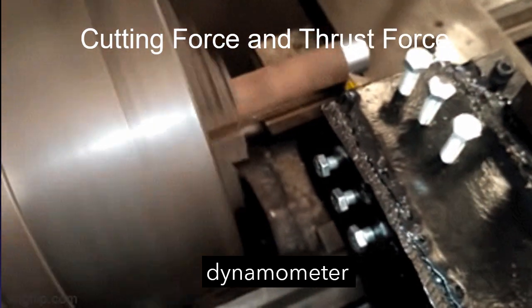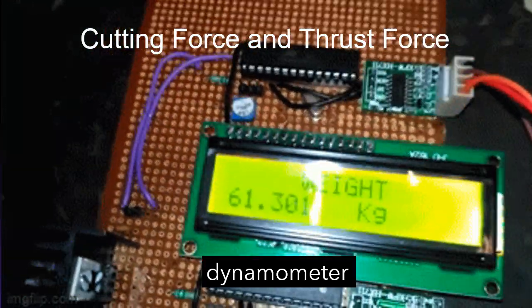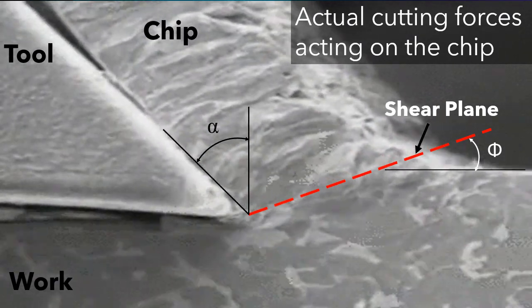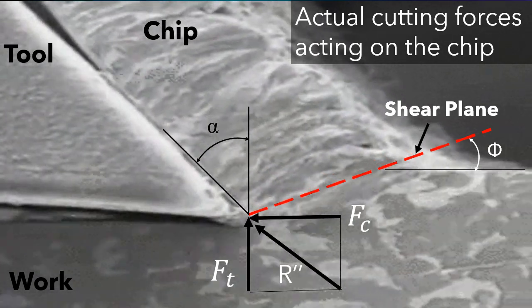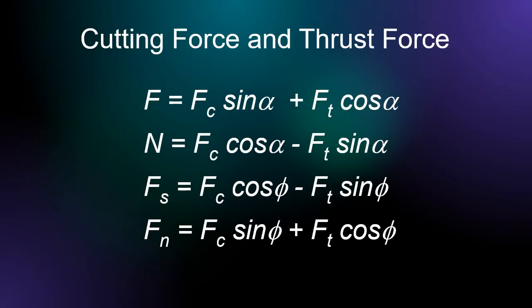However, it is possible to instrument the cutting tool with a force measuring device called a dynamometer, so that two additional force components acting against the tool can be directly measured: the cutting force and the thrust force. By using analytical equations, we can find the forces that cannot be measured.